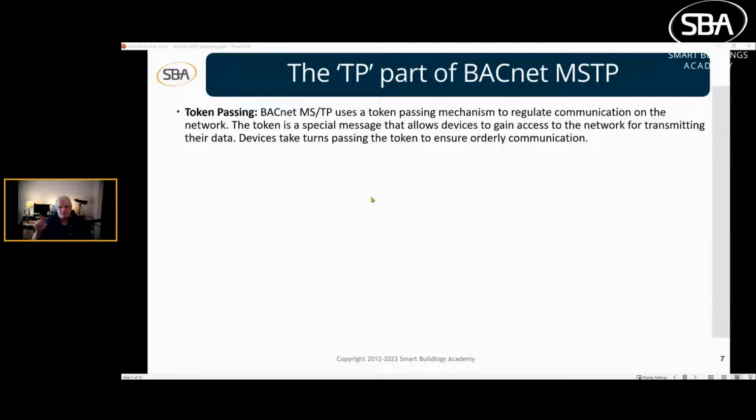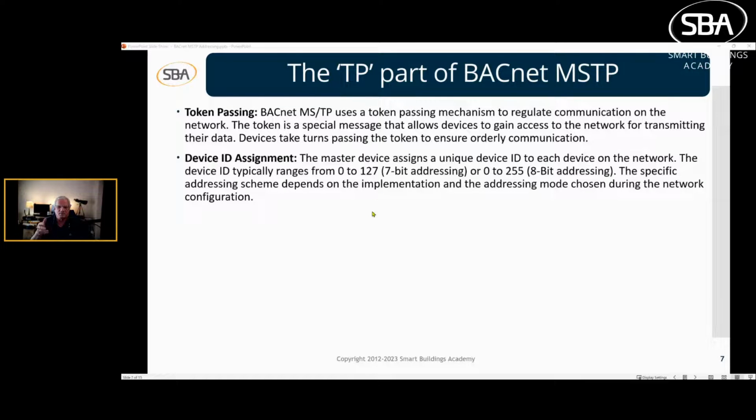And it has what's called a checksum at the end of it to verify. It's a code that's built, and we'll talk about checksum here in a second. It's a code that's built that both devices use to verify that the message is legitimate. So that's what the token does. It goes downstream, and it gives the device it's querying permission to communicate on the network. That's what the token does.